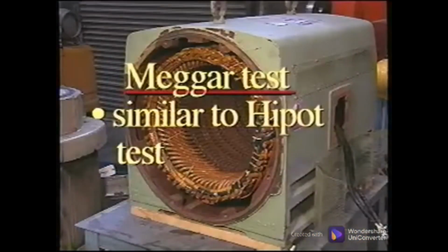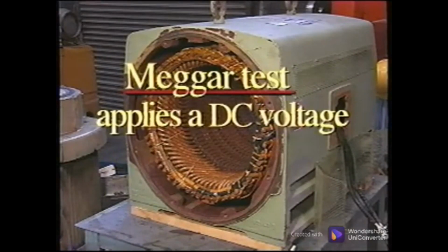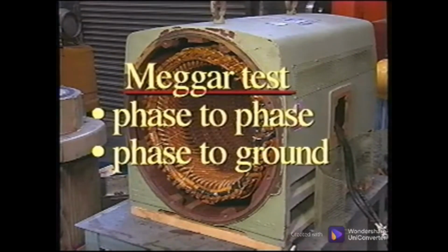The Megger test uses a megohm meter and is similar to the high-pot test. It applies a DC voltage to check phase-to-phase and phase-to-ground insulation condition, and these resistance values can be trended. The next section shows the tests and measurements that can be made without taking the machine offline.